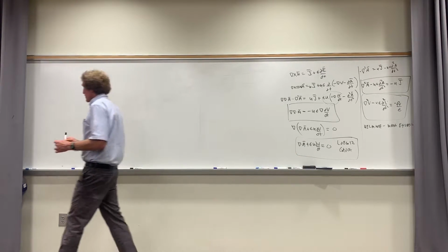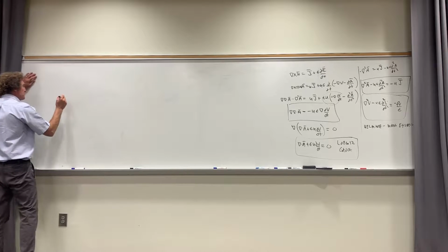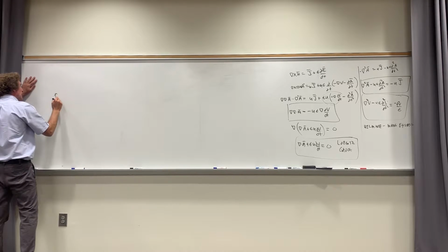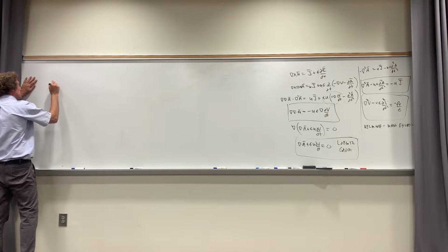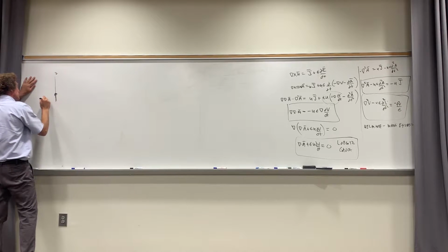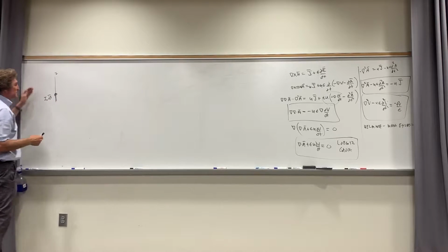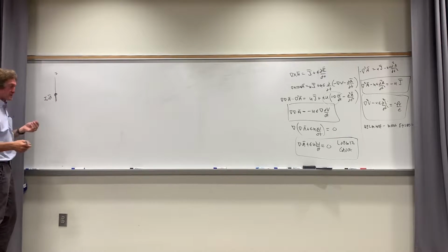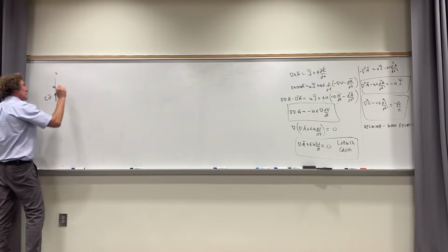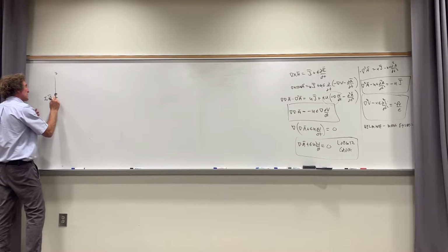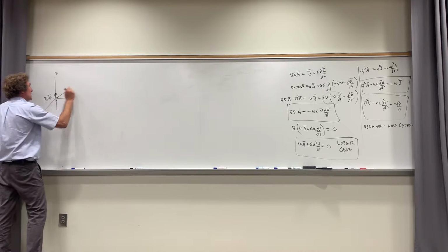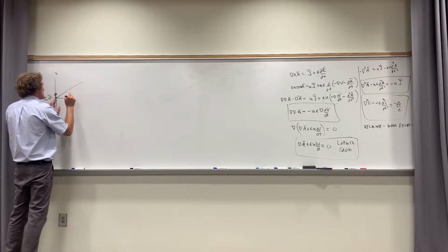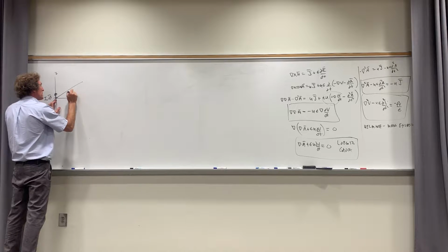Now, come over here, and say I have a current in the z direction, call this the z-axis, and this current is I naught dl. It's time varying, so it has a phase, that e to the minus j beta term that's going to appear, and this is going to be at the origin. And I come out a distance r away.